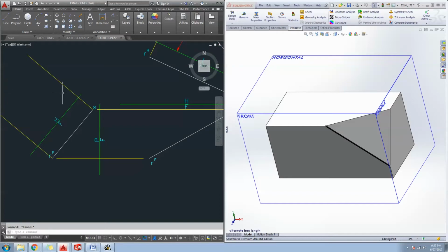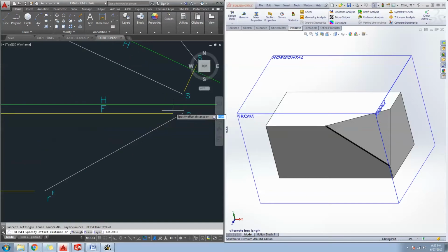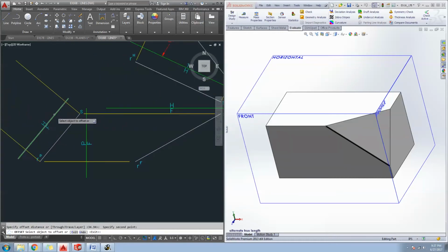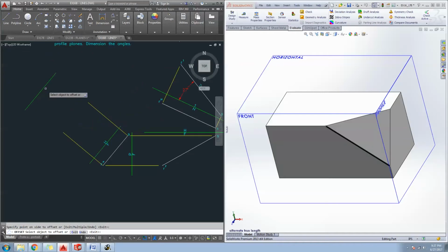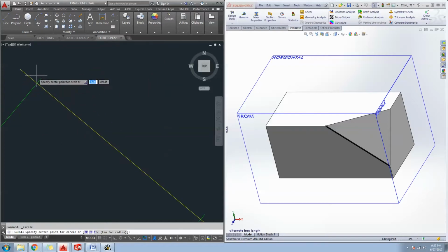Now we're ready to offset again. So this is the view we're interested in, so we hopscotch over, one view back, two views back. We're going to be doing our offsetting from this view right here. So this time we'll go from S again, there to there. From there, out. Hoo boy, it's all the way out there. That's pretty crazy. So we'll take that guy right there, and we will lengthen it. Again, dynamically move that guy out, and that's going to be the point S, right there.